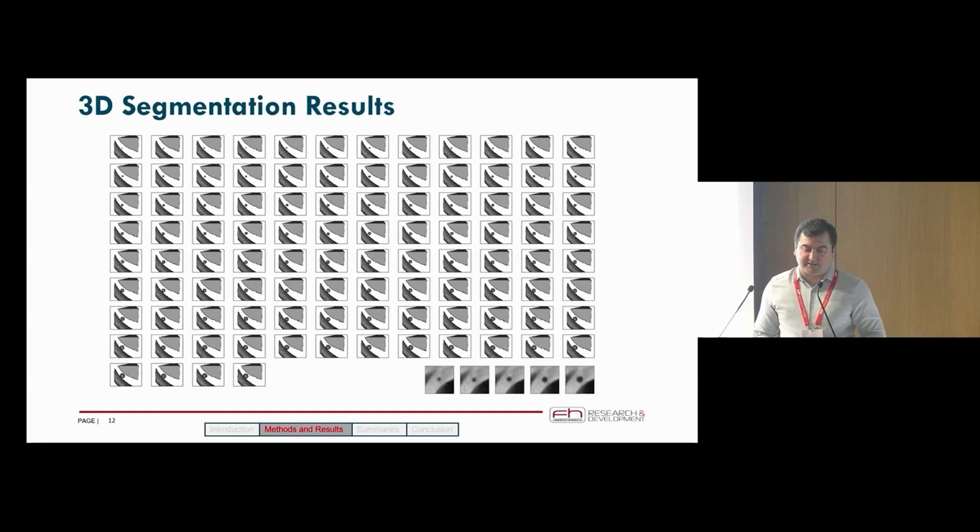So this is the first result we achieved. In the previous results, we were only able to segment 64 of the defects. Now three of the convolutional methods are able to segment 100 of them. You can also see the defects on the right-hand side in the CT images, and the voxel size starts from 50 micrometers to 1.1 millimeters in this case.